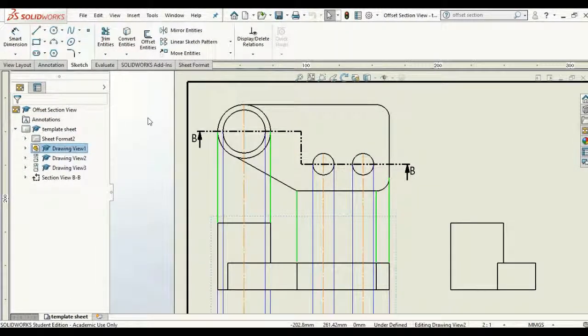When we look at our bracket in our drawing, we can see clearly our offset section line BB as it cuts our object like so. So it cuts across the object to about halfway. It is offset, it is bent at 90 degrees, and then it is offset a second time until it cuts through the entire piece. So after the cut is made, it's going to expose just this material here. So the material that's in front of the offset section will just be discarded.